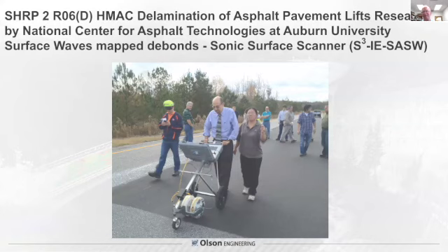It was extended to that, doing both impact echo and surface waves. And what we're doing now is an impact echo test on the left, or excuse me, on the left wheel here. And we line up the sensors so we look with a very close spacing of 6 inches between the wheel, not a foot down. That gives us a surface wave result.